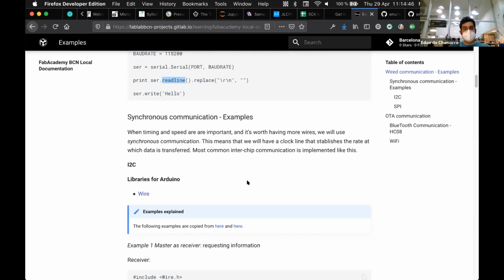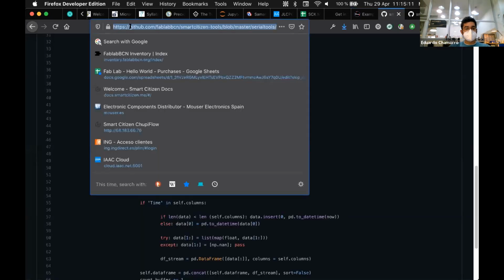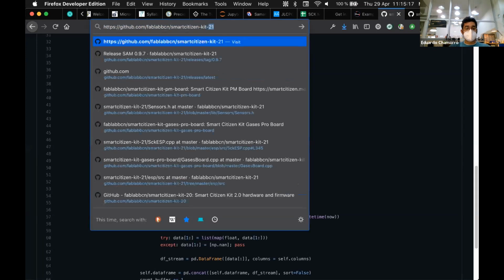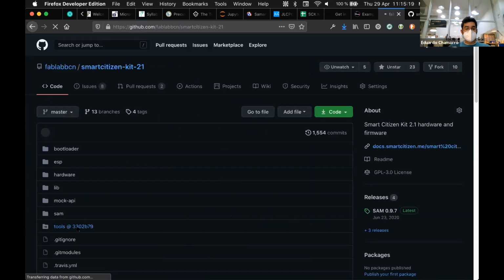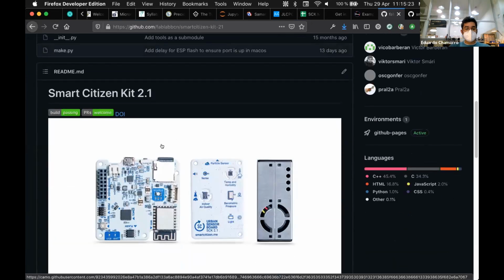Storing in the SD card normally is going to be using SPI communication. So at least you need SPI, and because of that, you need a high speed and high memory microcontroller. You could do that, yes, but it's somewhat easy if you know what you're doing, but it takes a little time. But if you want to do it, I encourage you to go here. And basically, there is already a device that has an SD card and saves data in CSV.